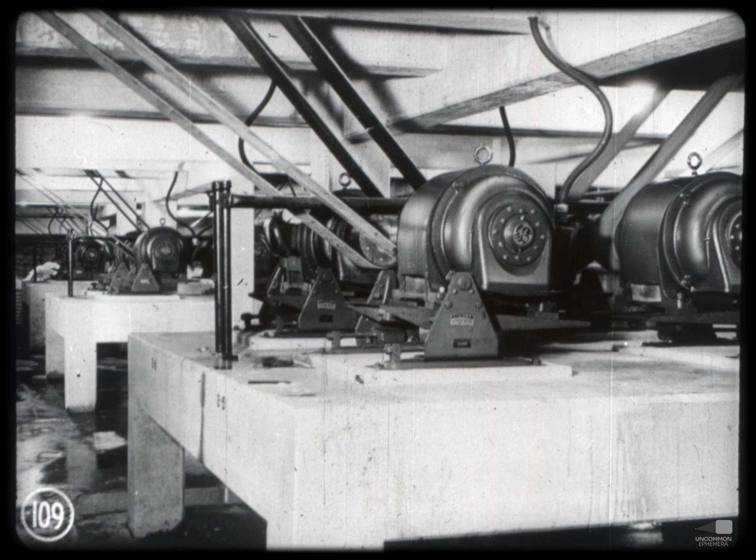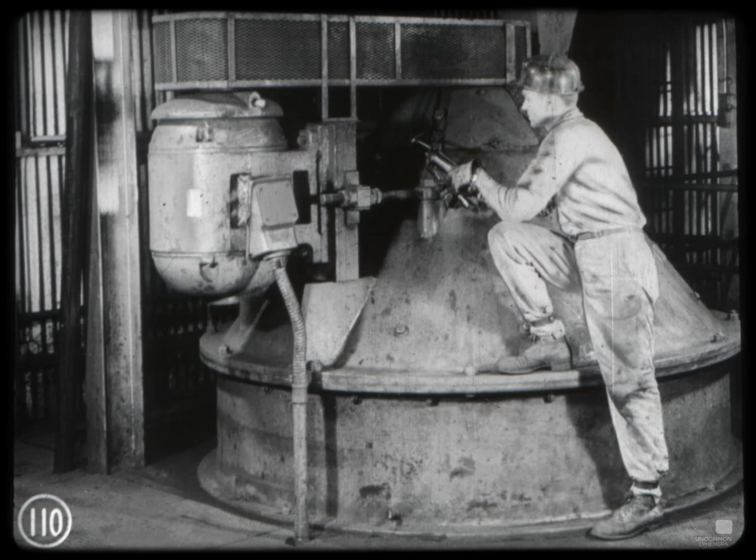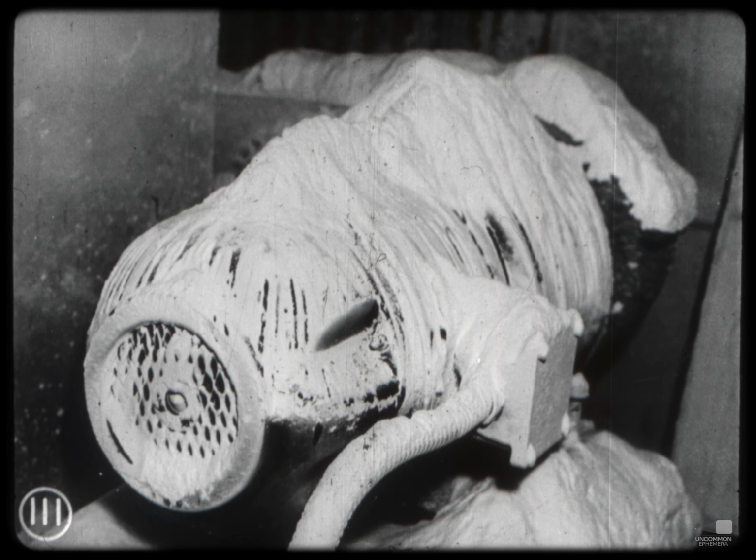Just as important as the enclosure is the location of a motor and its care during use. By placing these paper mill motors on stilts, they almost certainly will last longer because they're away from the danger of splashing liquids. Again, mounting this motor off the floor helps protect it from dirt and from being hit by moving machinery. Even though this totally enclosed motor is designed to keep out dirt and oil, better results and longer life could be expected if it were cleaned up.